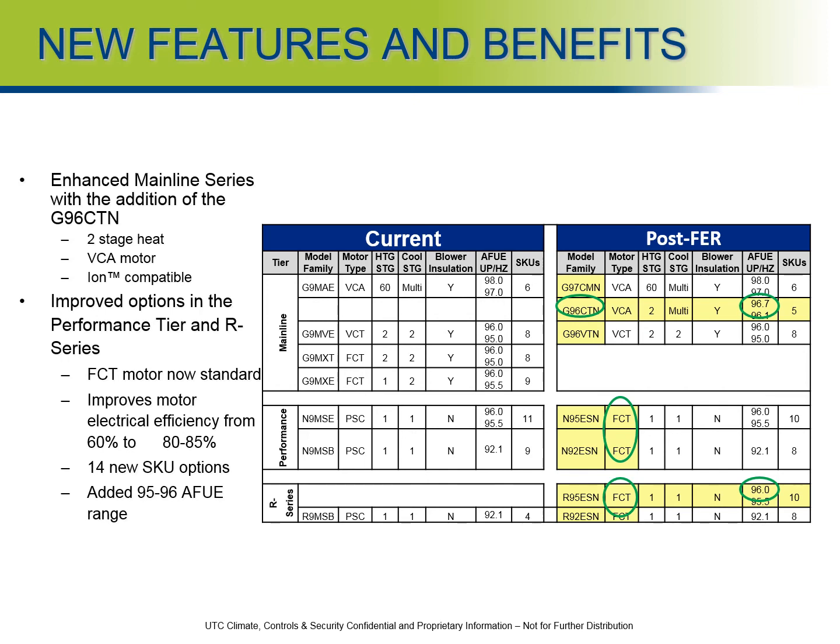Real quick, let me revert back to the G9 MVE with the variable constant torque motor. That motor you are going to now see in the G96 VTN, Victor Tango November. So that is the new nomenclature for that specific furnace. And now back to our X13 motor. X13 essentially was a brand when it was initiated and initially manufactured. X13 kind of became the standard default name for that fixed constant torque motor. But the true name for that motor is a fixed constant torque or constant torque motor.